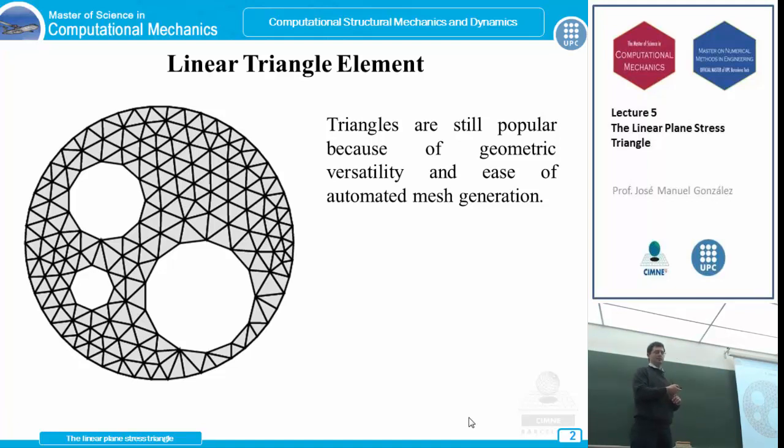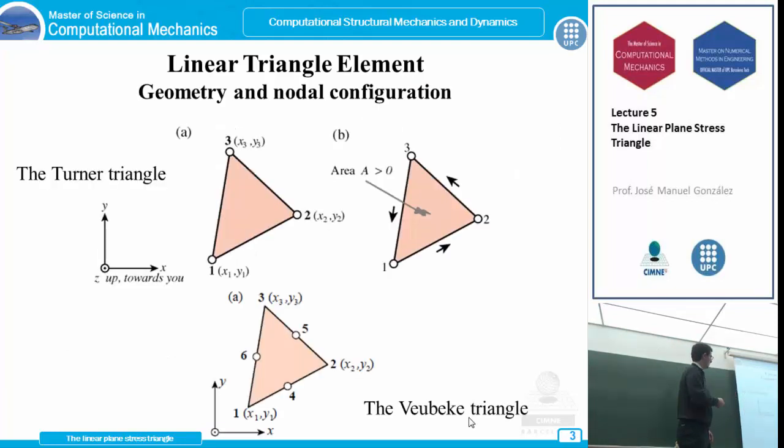Okay, but usually in very complex problems, we use quadrilaterals or hexahedra, which are much more reliable. If you want to get a high level of accuracy using this linear triangle element, you must use a lot of linear triangles in your mesh. But for our purpose, which is to explain the formulation, it's very good because it is a simple element like this one.